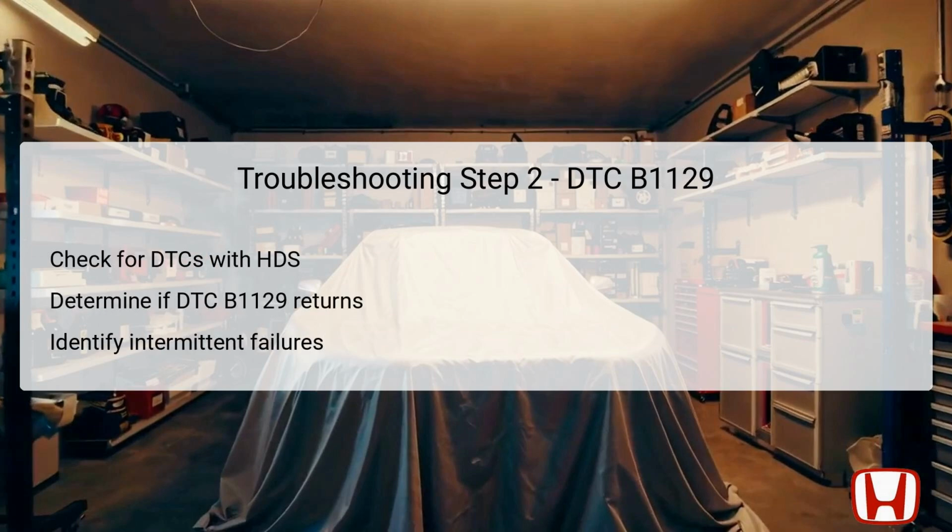After performing the initial series of checks, the next step is to check for DTCs with the HDS once again. This step is vital to see if DTC B1129 will reappear, which indicates an ongoing issue.